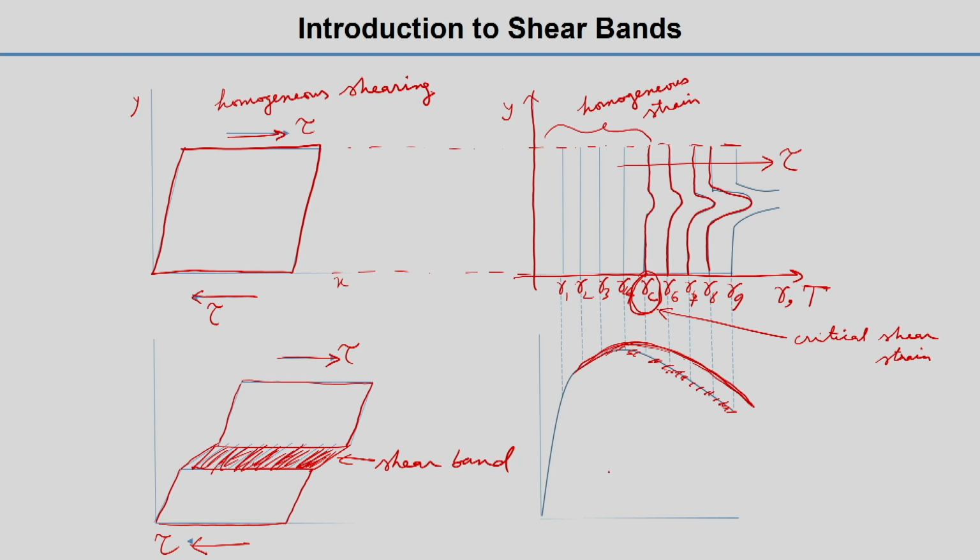And then the last figure is the stress strain diagram, shear stress versus shear strain, and you can see why I said it is a little incorrect, because the maximum stress, tau max, should be at gamma C. It should correspond to gamma C. So we had made a mistake while drawing it. Now tau maximum should be at gamma C.